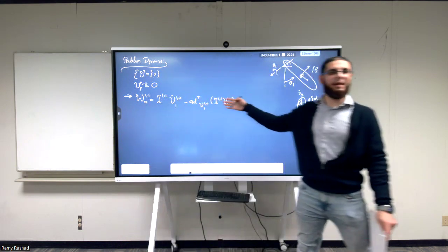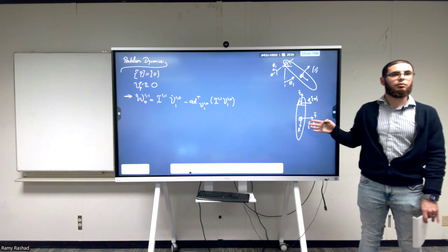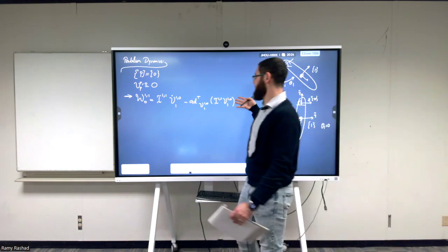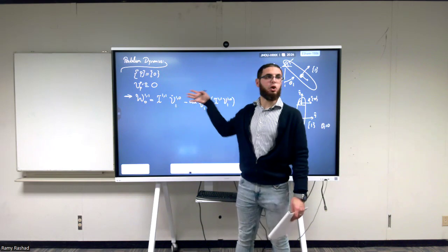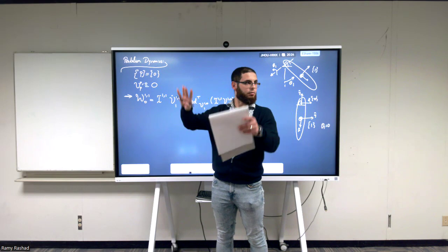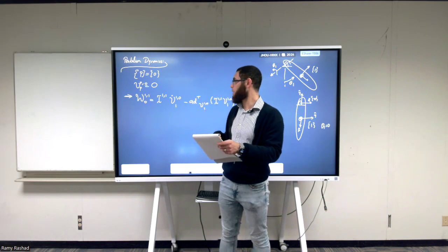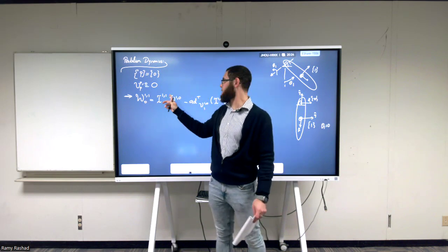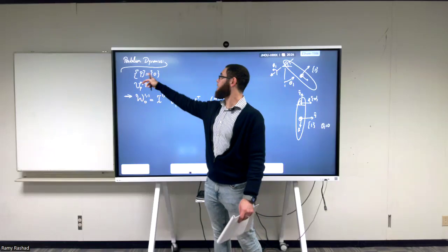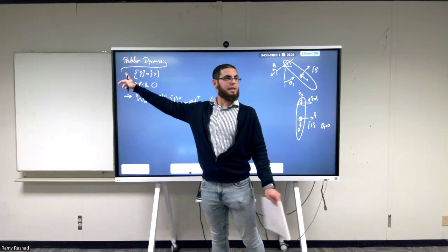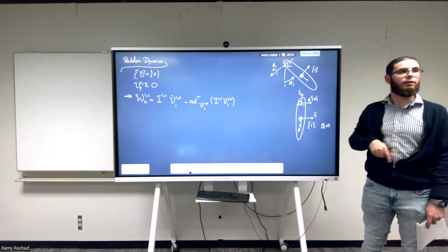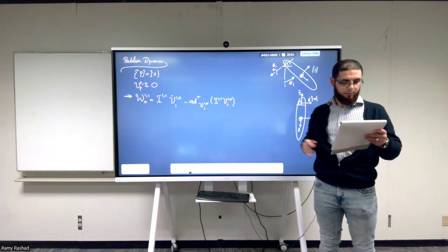This is exactly the same expression that we had in the first part for the child. We just wrote it with V and V dot as an input on the right-hand side, and the wrench as an output. We wrote it in a differential causality, so in the inverse dynamics equation. I replaced all of the C's by 1 and all of the P's by 0, because the P here is the 0, and the C is just the 1 link. So this is the equation that we have.